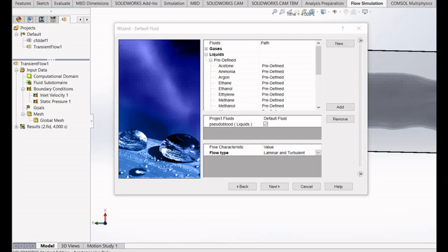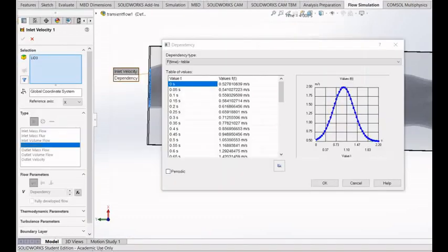Since blood flow is not constant, non-zero at any point, a Gaussian bell curve approach was taken in order to simulate as close as possible the pulse nature of the blood flow in the aorta. After fulfilling those inlet velocity initial conditions and the pressure at the end of the aortic branches, we are ready to start the simulation and wait for the corresponding results to pop up.